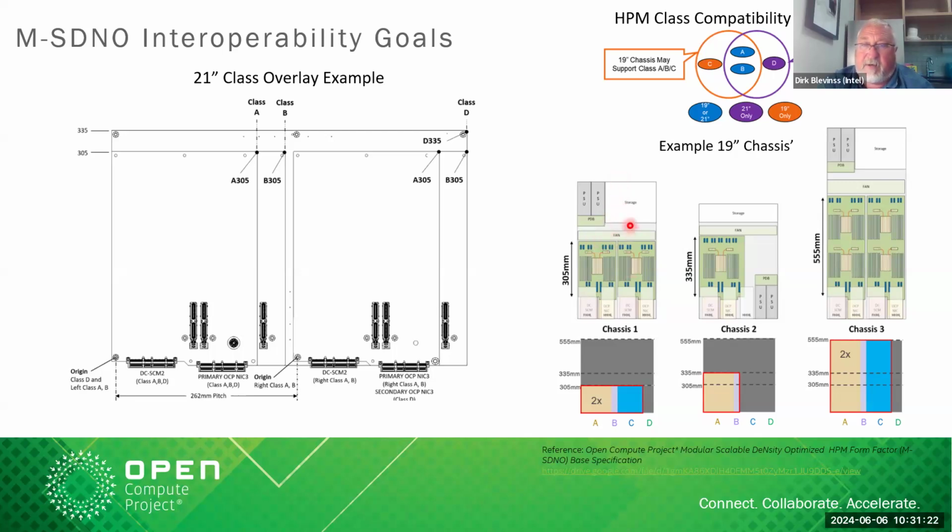Our scenario has been cold plate, and it's been into solutions where understanding the nozzle sizes that would be required for the quick couplers, how power is delivered, where it's delivered at, all those kind of things for both 19-inch and 21-inch, as well as building out very detailed models to understand exactly where, as I was saying, the DIMM cooling apparatus, mounting apparatuses would go, as well as the heat sink mounting apparatuses, and then all the way up to the add-in cards or the riser cards.